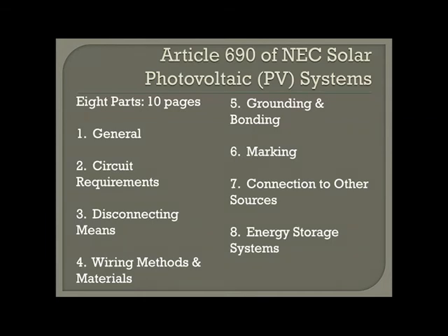I suggest as an electrician, I'm talking to you as electricians because I'm electrical inspector for the city of Lincoln. So most of the time the code talks about 40% capacity inside of a junction box, panel board, gutter. So think about that 40%. That's all you can fill that up to. So most of the time, especially if you have electrical equipment before the 1980s, they never had enough space in the panels to start with anyway.